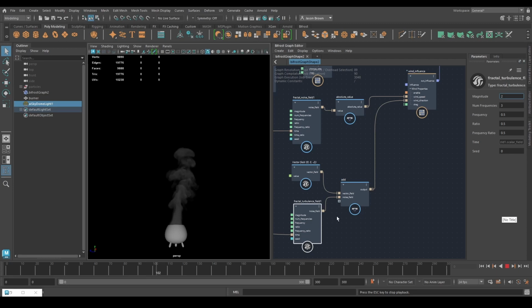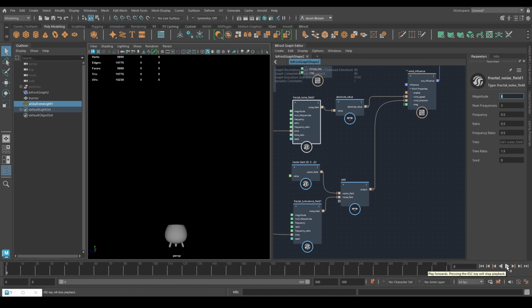So one way to get this looking a bit better is maybe for the wind direction. The speed is good. Just stop that. For the wind direction, what I'm going to do is just lower this frequency, and then we'll take another look. I think I'll push the wind speed up as well. That was probably a bit far. Let's try 6. And you get used to this changing of values and looking again as you're building anything to do with simulation, really.